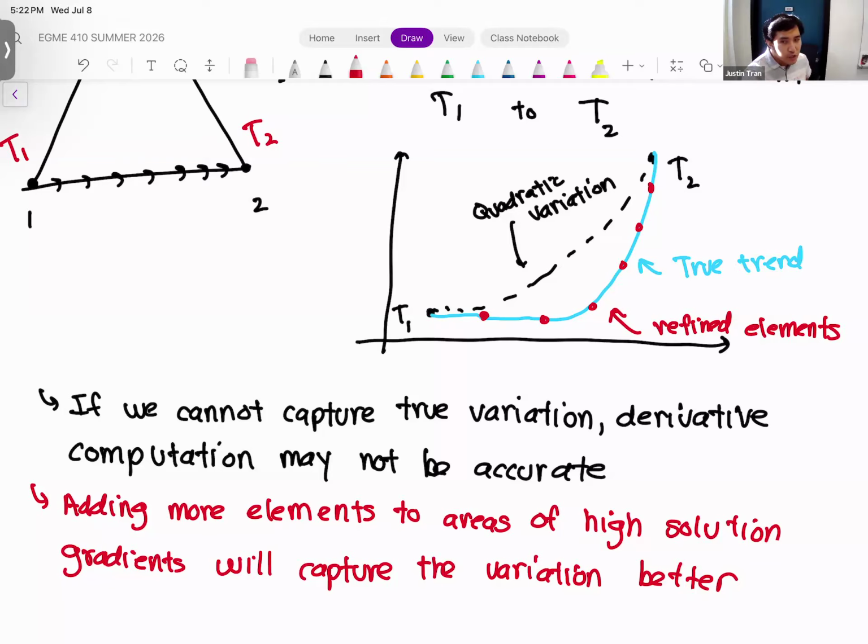And so you want to be strategic in terms of where you're adding those, where they're going to have the most impact. Because just by saying that you have a mesh of 5 million elements doesn't really tell me anything. It's not about the raw number of elements. It's about where you're distributing them and where they're most effective.